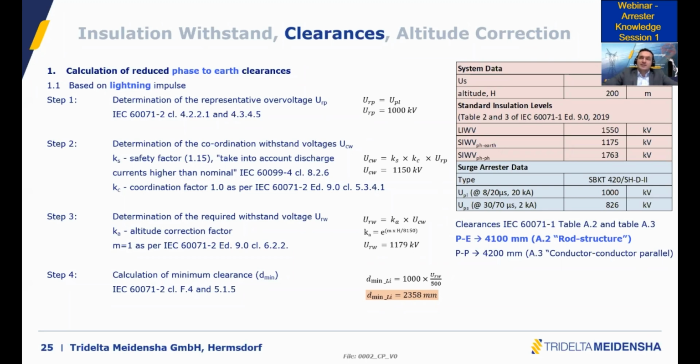And those insulating bases have a maximum withstand voltage. Typically, with very fast front lightning overvoltages, if the distance from the bottom of the arrestor to the surge counter is too long, there is a probability that the base flashes over and the information is not recorded by the surge counter. So typically, values will depend on your insulating base.